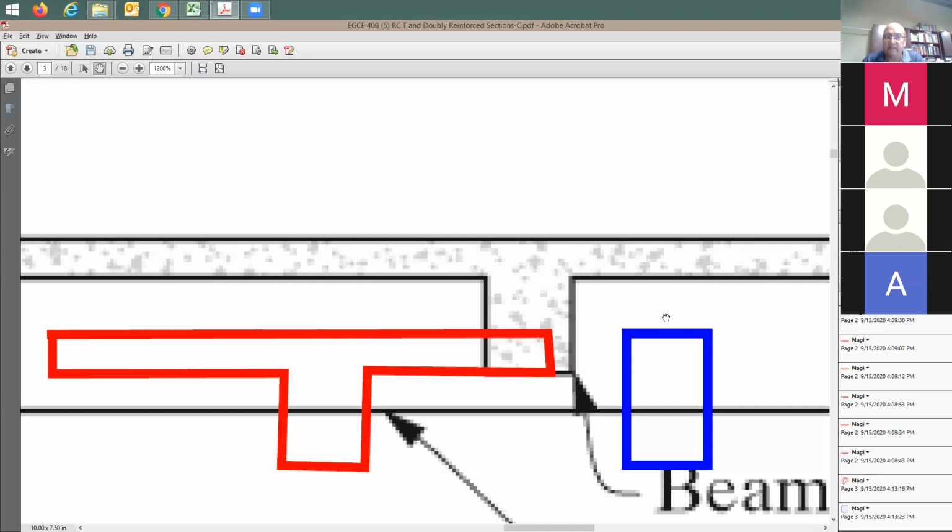In the final design stage, to determine the actual strength of the beam, you're going to do it like this, T section. So you're going to have a little bit more work, detailed analysis, but you know what? Now you know the depth, you know the width, and approximately the reinforcement is kind of set. Now we understand why we can ignore the fact that all beams are T beams and just consider them to be rectangular sections, just for simplicity at the beginning of the design.